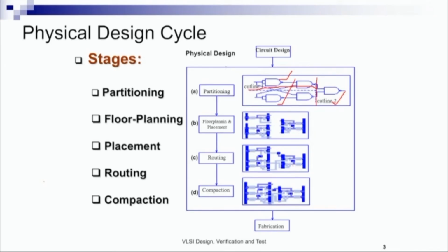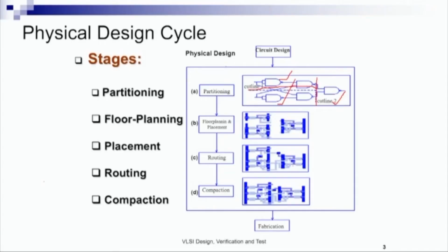And we have to obtain an optimized layout which tries to minimize the chip area, say, could be minimizing the critical length of a wire in the whole design, and to maximize performance in the face of constraints such as limited area, number of metal layers or routing layers available, etc. And hence the whole physical design process has been divided into a set of stages or steps.